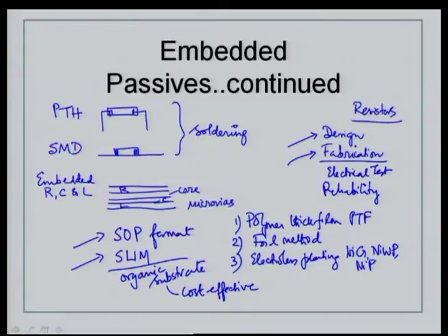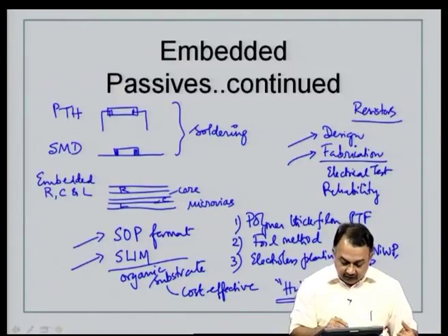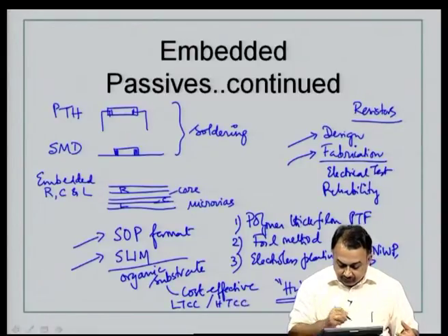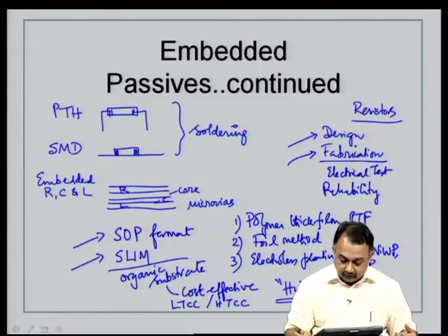Now, if you recall, I also talked about hybrid circuits in the last class, where hybrid technology has been known much earlier, and especially the thick film circuits talked about screen printing thick films of resistors, copper conductive based capacitors or inductors, and then co-firing them using LTCC process or HTCC process, and then realizing modules including multi-chip modules.